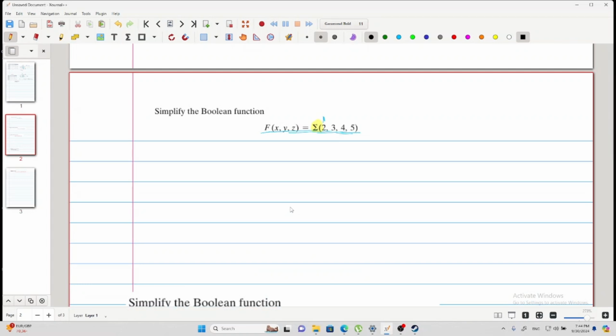Okay. Now after knowing what this is, let's see how to actually construct the K-map for three variables. So let's begin. Bismillah. We have this and this. So first we choose one variable to be here on the side, so we have here 0 and 1, exactly like two variables. Then the difference is going to be here, where we want a specific order. First we have two variables, y and z. We write 0, 0, then 0, 1, then 1, 1, then 1, 0.